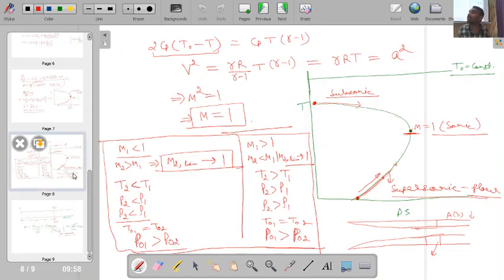Okay. So now it is important to make one clear difference. In case of the Rayleigh curve, what have we done? We said that if I start from a supersonic point and keep on adding heat, I will reach a point of sonic condition, and from this point, if I have to follow the curve, then in place of adding heat, in the remaining portion of the length of the pipe I have to cool. If I start cooling, then I will actually be able to reverse the direction of entropy. Okay, because in that case, if I am removing heat out of the fluid, then the del q by T term will be negative, which can decrease the entropy value, and I can follow this curve.